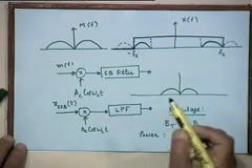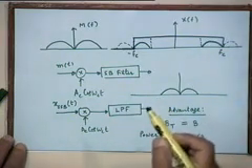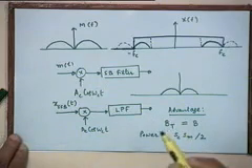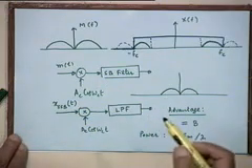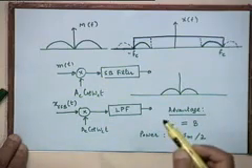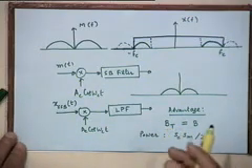And designing high Q, high quality factor tuned filters using conventional passive components like inductors and capacitors is extremely difficult, right? They will typically be very large order filters, and remember, no matter what you do, how ideally you construct your inductors and capacitors, there will be losses, right?